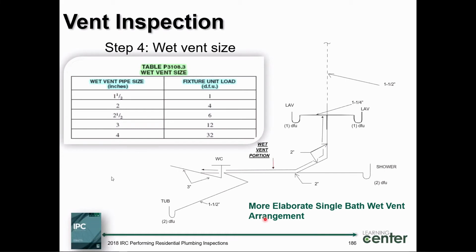It's not too hard, is it? Look what's happening here. When I see a diagram like this, I always look for the dry vent. Where's the dry vent coming off here? And where is the end of the wet vent? Remember, it starts at the juncture of the dry vent, doesn't it? Right? Yeah. We move down in the direction of drainage, down from the dry vent juncture to that point. We go on, go beyond, and it ends right here, right at that point there.